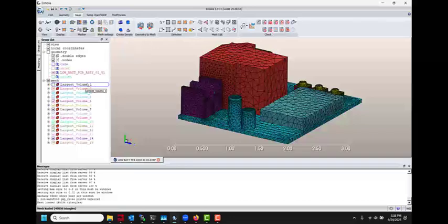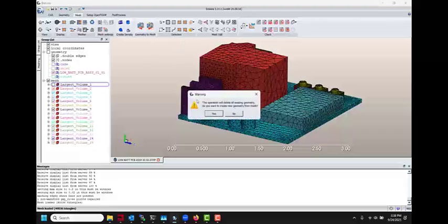So the first thing that we need to do to set up the volume mesh, now we've got our surface mesh and our volumes all defined, is transfer this volume information over to our geometry. Our geometry is where we're going to be applying the CFD boundary conditions from. We can do this with, watch what happens when I do mesh to geometry here.